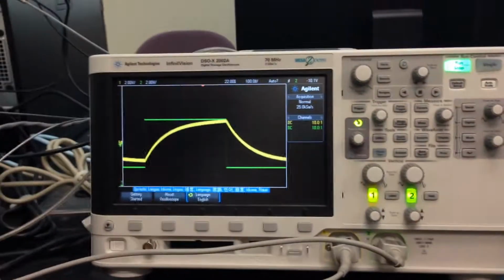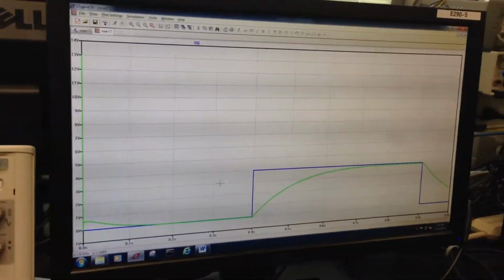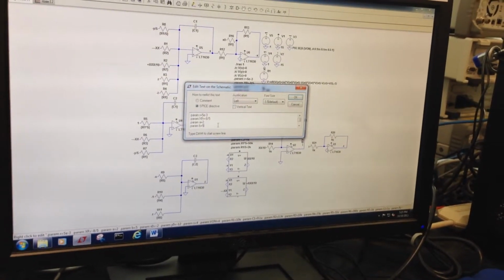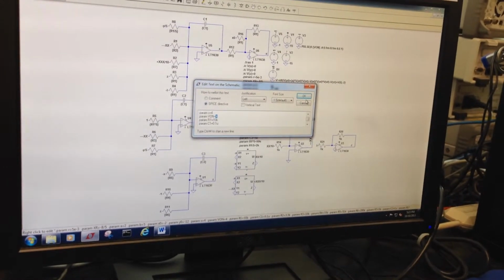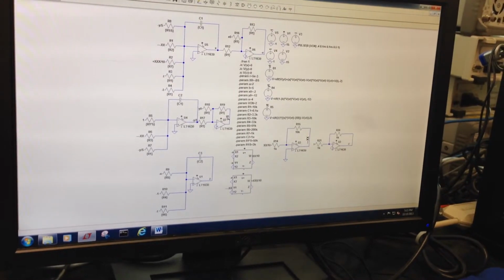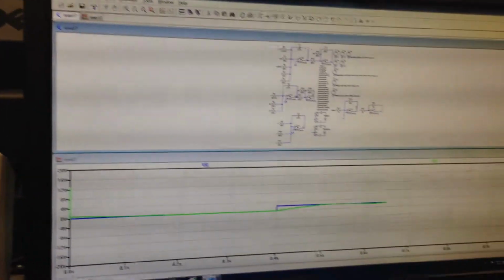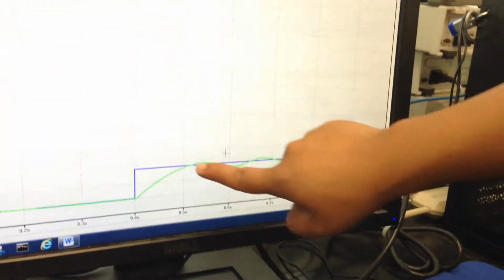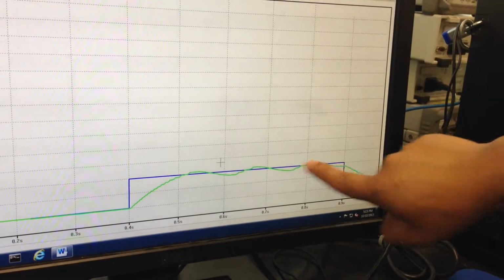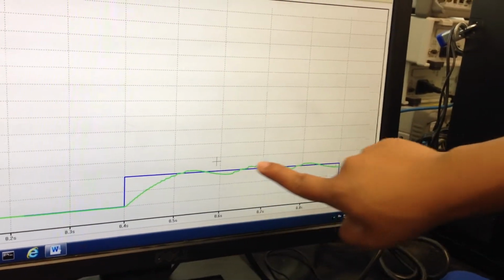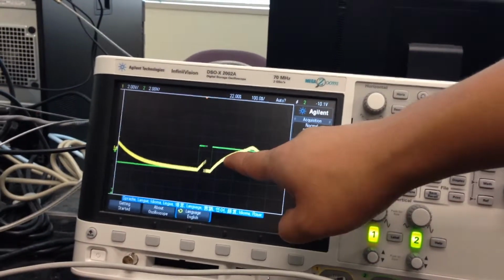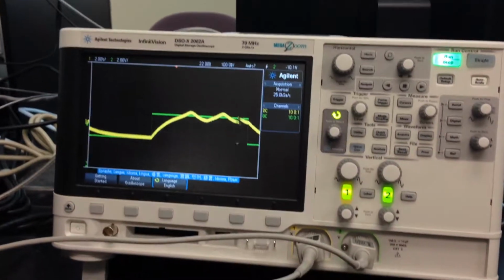You see the curve for the Z at 4 volt input. Now for the 2 volts. That's for the Z. You can see that for the LTSpice simulation at 2 volts for Z, the curve kind of becomes hilly. It's not the defined straight line of the previous one, and that curving is shown in our oscilloscope output too.